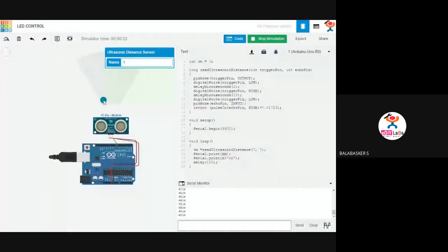You can move this ball in any of this. See, the maximum value is 299 centimeter. Here it's 300. Again, when you go here, it's around 200. Whenever I move out of this distance, there won't be any reflection. So automatically the signal will be lost. If the signal is lost, your value will be above 330. So we can declare that your ultrasonic signal has been lost. Whenever it's in this limit, it detects and gives the value.